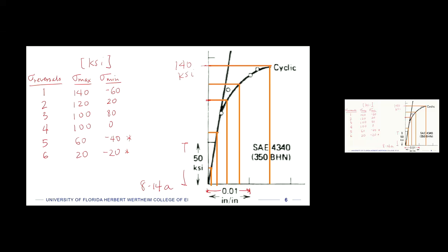But in this case, we're in low cycle fatigue, and we really are just going to use what we know, which is this stress strain diagram, because we have to translate now these stresses into strains so that we can calculate the fatigue life for each of these cycles. So I've put some of the levels on this cyclic stress strain diagram that we would need corresponding to these. And I found in the book, this diagram is, I think, going to be like 2 inches high. And so in order to go in there and find distinctions between all of these different values on the y-axis and then look up what are the strains on the x-axis, the book does not give us a very good chart to do that, which is only this one here.